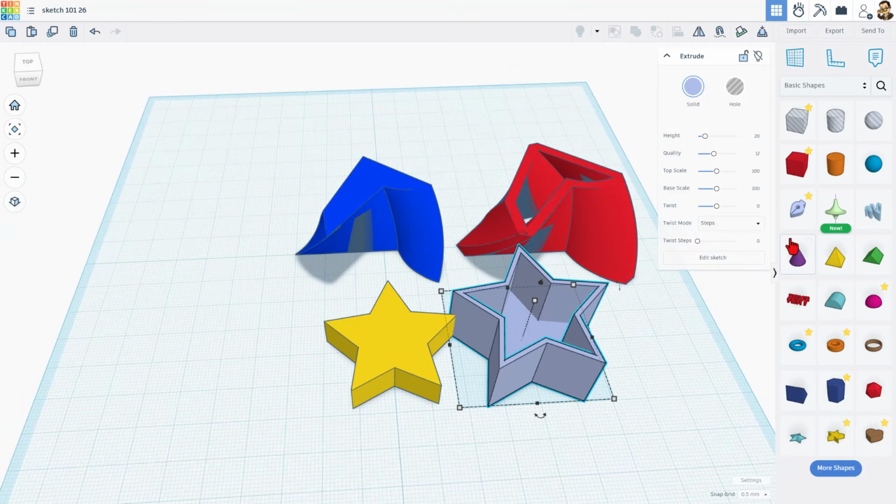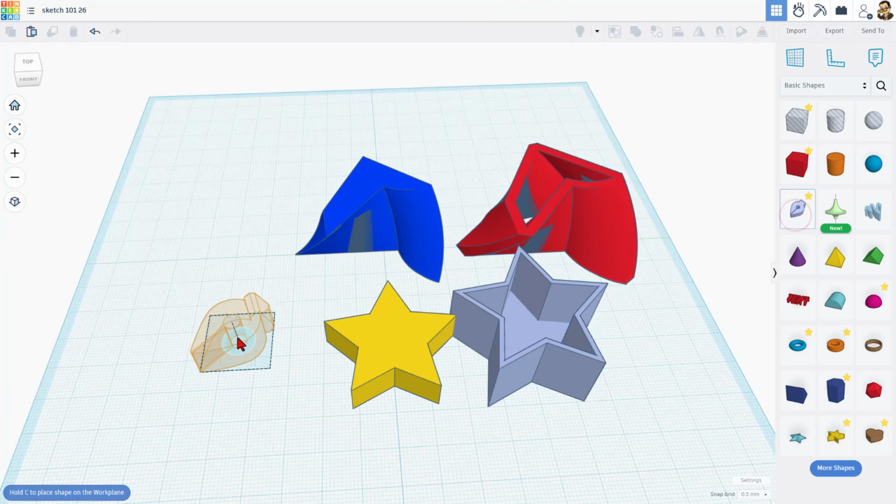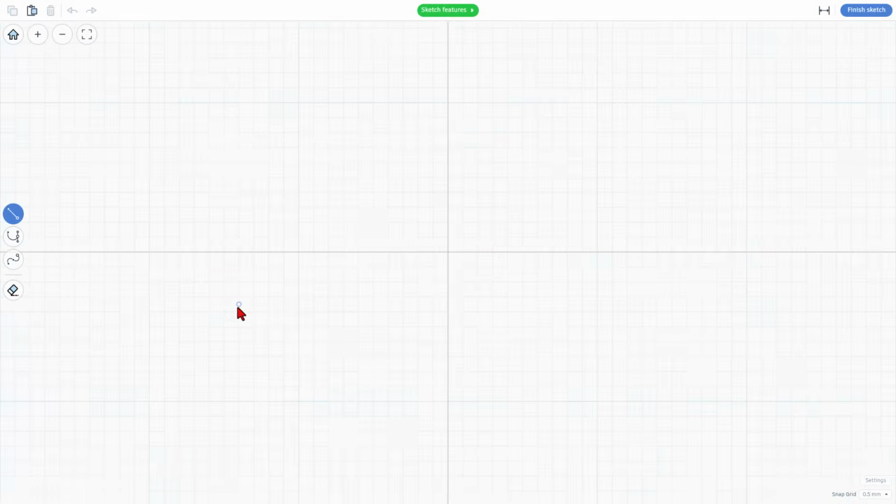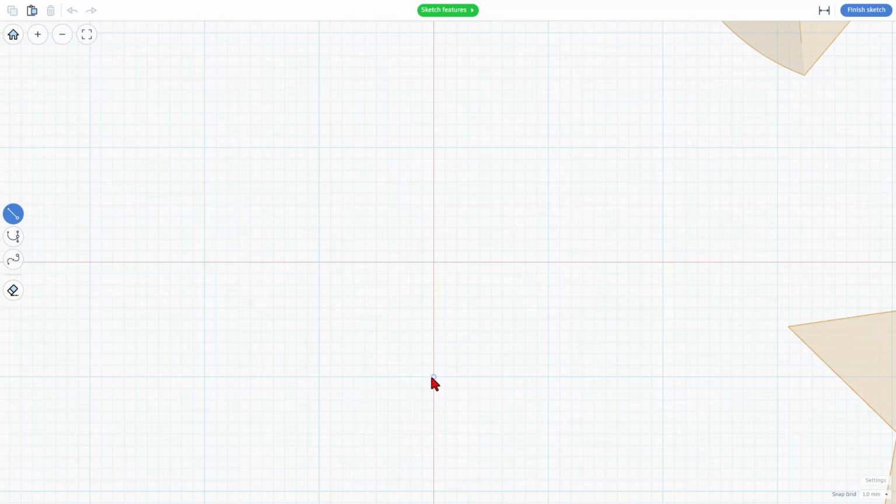We are going to do one final trick for today. Bring out your sketch tool. Once again, find a 20 by 20 spot. Click and set it down. Now to build this box, I'm going to make it 20 by 20, but then I'm going to show you how to adjust it. So right here is center, center. I'm going to just move down to this box, and I'm going to move 5 over.